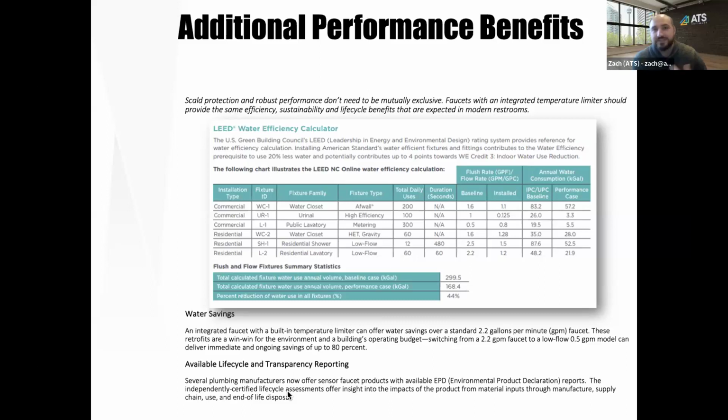Well, it comes down to Legionella control. It's a situation where we have conflicting standards. On one hand, we're trying to provide hand washing at a comfortable level that allows people to wash any germs off their hands. But on the other, we're trying to protect our piping system and prevent any bacteria from living and growing inside our pipes.